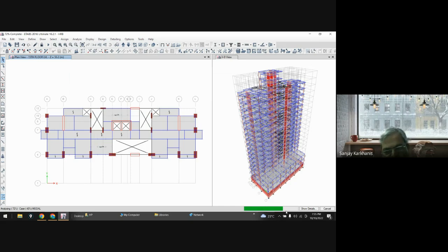See, it will take a little bit more time. This is called the first run. After this first run, first we'll check the base shear calculated by EQX, EQY, then the base shear calculated by Spectra X and Spectra Y, and we'll rectify the scale factor, and then again we will have to reanalyze, right?